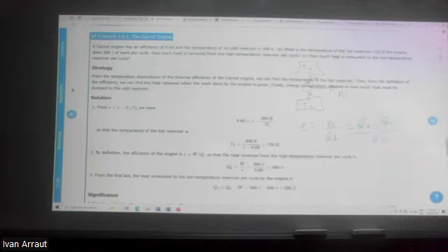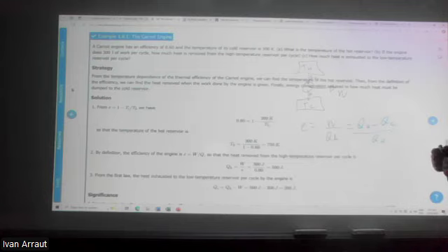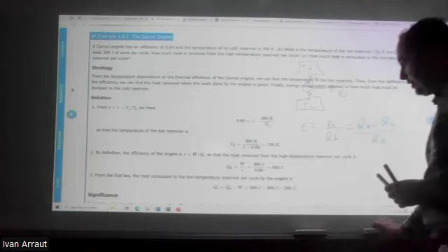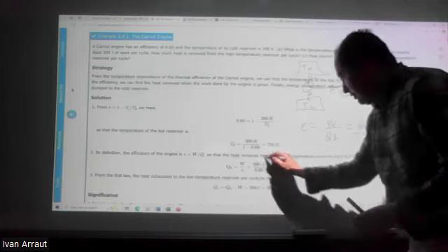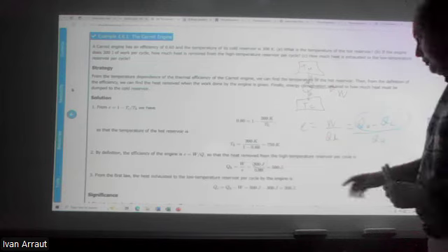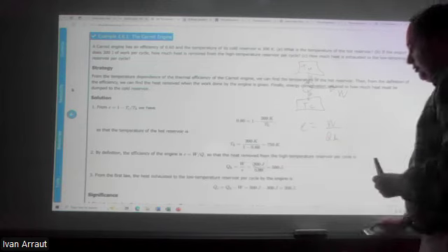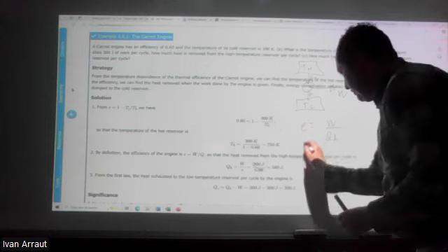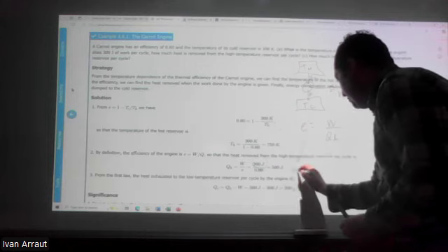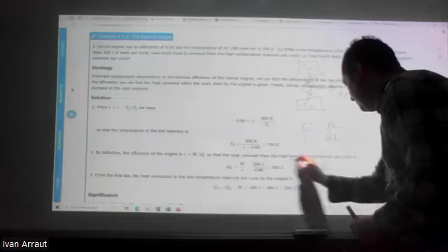It's valid also. Or you could use the original formula and start again. It doesn't matter. Anyway, you have 300 joules of work, which is this difference, divided by the efficiency, which is 0.6, and that gives you the Q heat, 500 joules. Solving here, this is not difficult, no? Q heat equals the work divided by the efficiency.